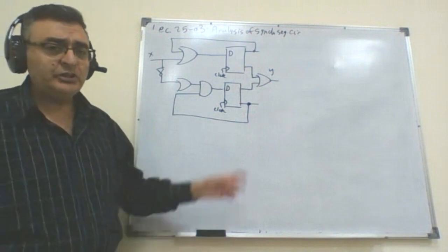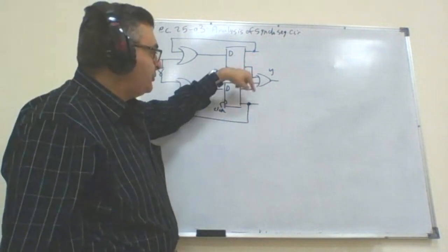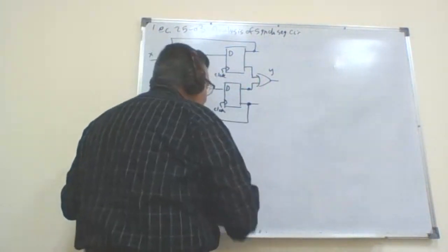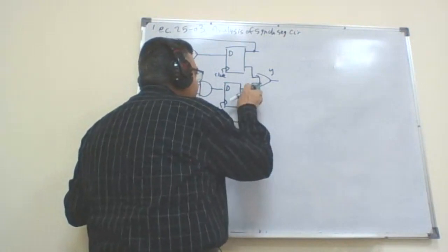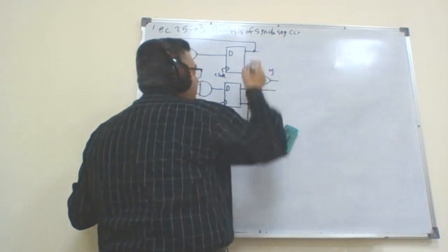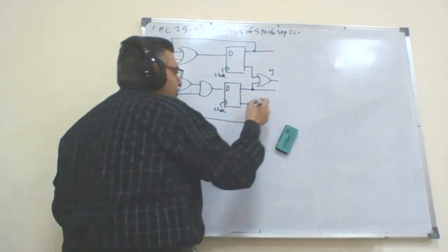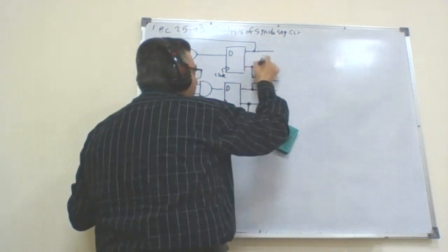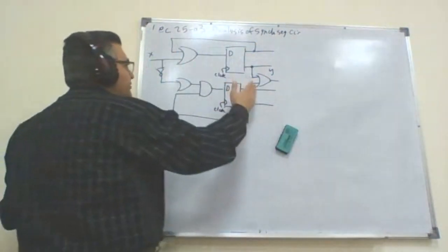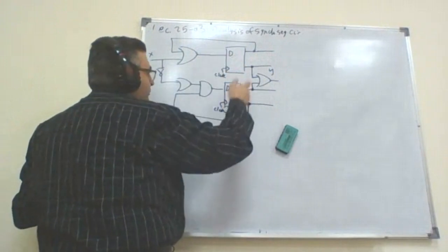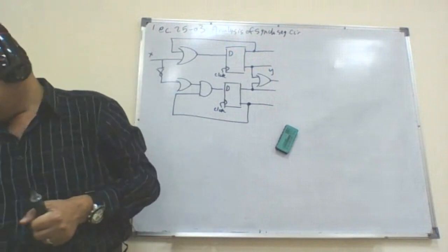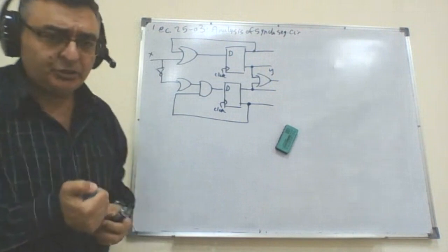As you can see here, in addition to the output going out from the flip-flops, we also have the output that is not directly connected to one of the flip-flops, which is the output Y. As we mentioned before, the Q's of the flip-flops, the outputs of the flip-flops connected to the feedback, are considered as inputs in my analysis.